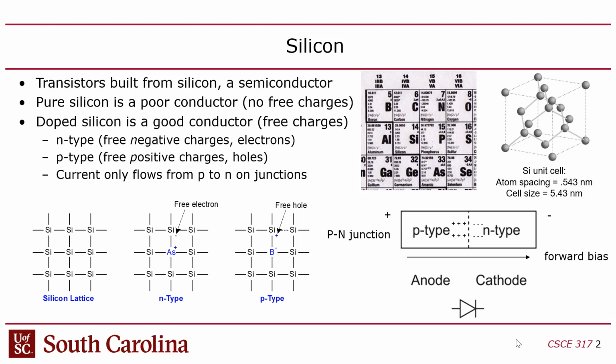If, on the other hand, you reverse bias, meaning that you put the voltage of the N relative to the P as positive, right? What ends up happening here is that the positive voltage of the N side, the cathode, is going to repulse the hole charge carriers away in the P-type side, right?